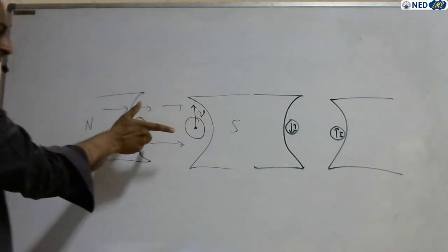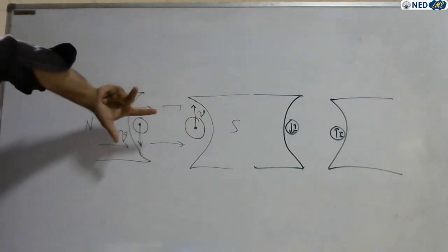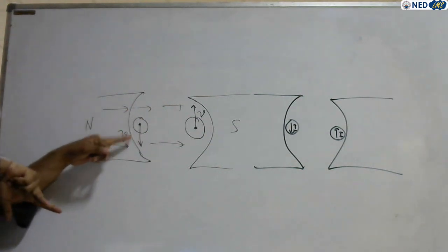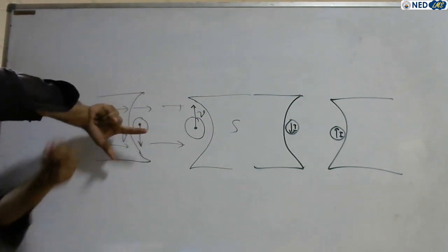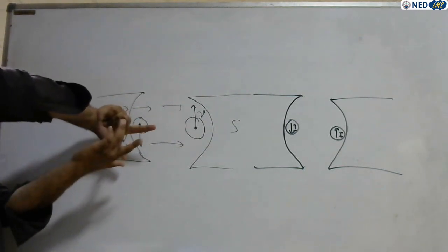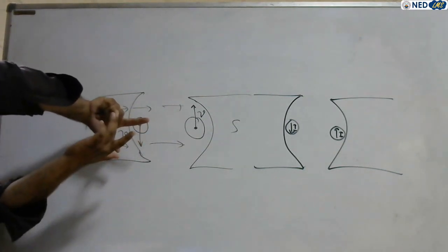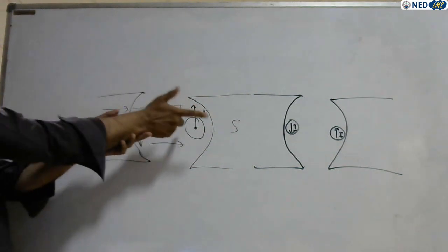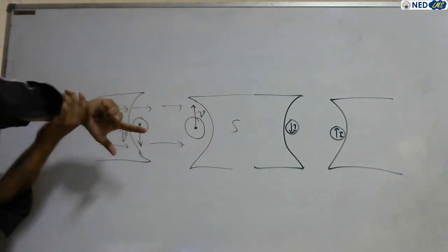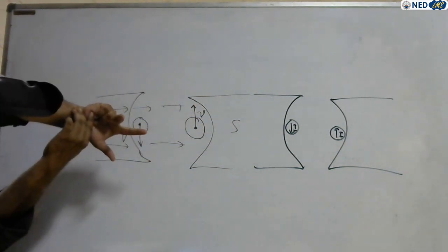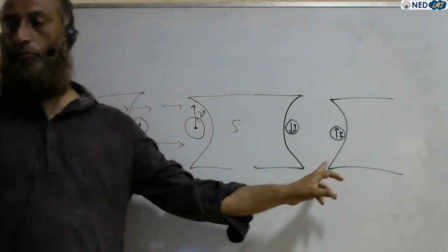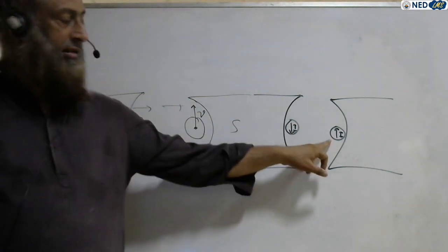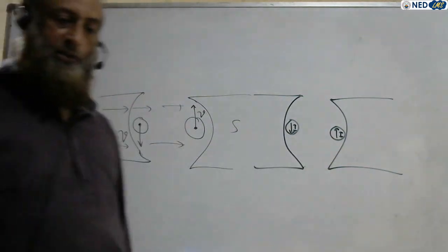And if you alter the velocity, for example like this, see, the velocity alters, right? When you alter the velocity, your middle finger comes out, that is, the positive of the induced voltage is at terminals out, right? Here terminals in and here terminals out, because the velocity is changed. See the velocity direction. Similarly, the rule for the motor, see, in these conductors which are under the influence of the south pole,